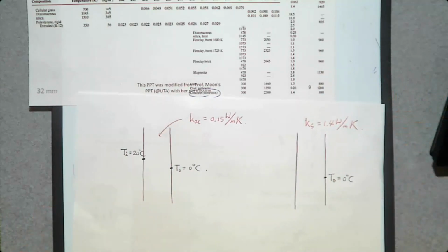What does it mean? The one has this low thermal conductivity, the other one has this high thermal conductivity. That means the rate of heat transfer through this wall is going to be almost 10 times less than this one. So if you want to save energy, trying to minimize heat loss through the wall, then you need to use this aerated concrete block. However, of course, this one is going to be more expensive than this one.